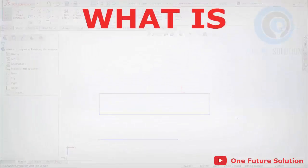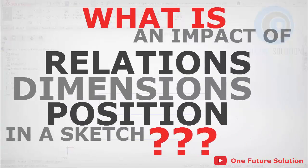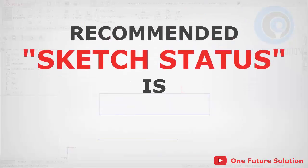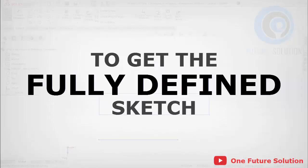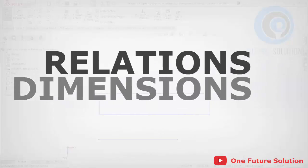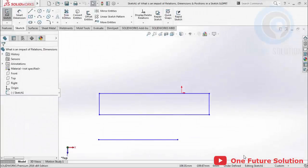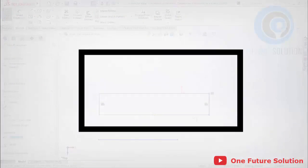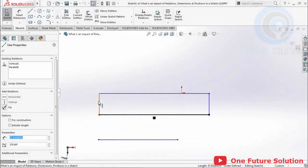Number 6. What is an impact of relations, dimensions and positions in a sketch? Now, we know the recommended sketch status is fully defined, and to get a fully defined sketch, we need to adjust the relations, dimension and positions of the sketch geometry. In this case we already adjusted the relations of the sketch geometry to get the rectangular shape. Now the rectangular shape cannot change into another shape like parallelogram, trapezoidal or else, except if we delete the sketch relations and modify the shape.